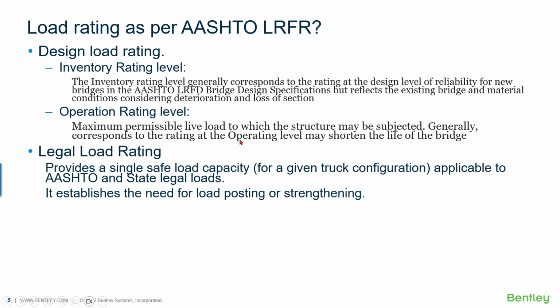The legal load rating is just the simplest one. It provides a single safe load capacity for a given truck configuration, usually the legal one, applicable to AASHTO and state legal loads. It establishes the need for load posting and strengthening. Typically, if it cannot carry the legal loads, we have to diminish the maximum loads or need to strengthen the